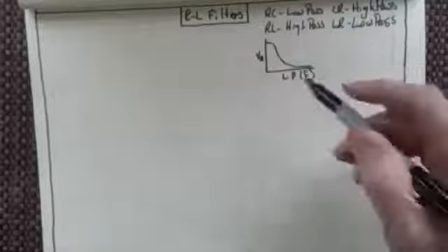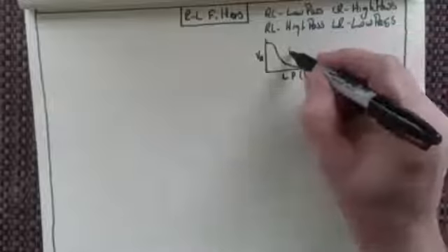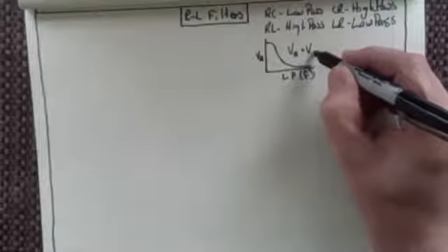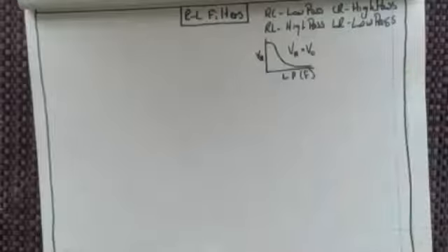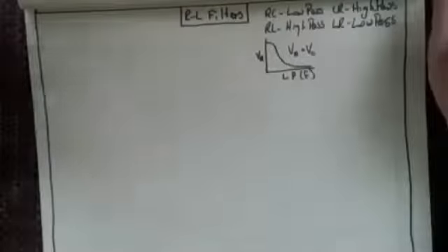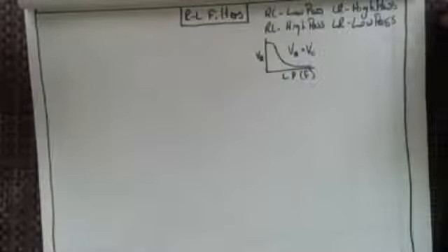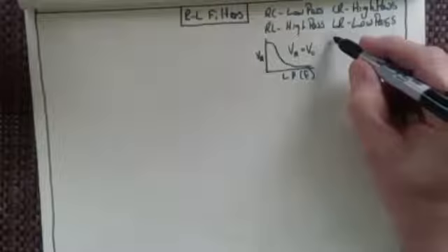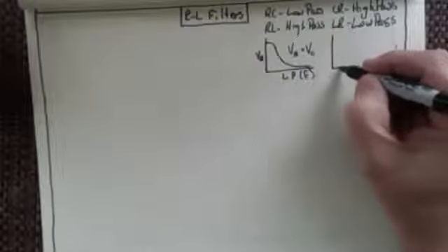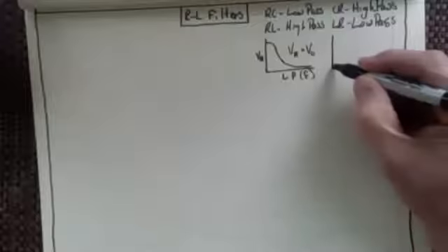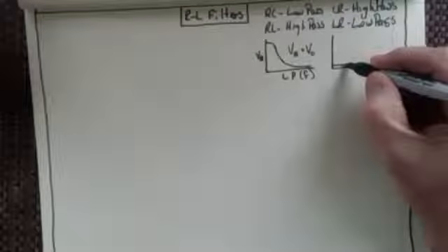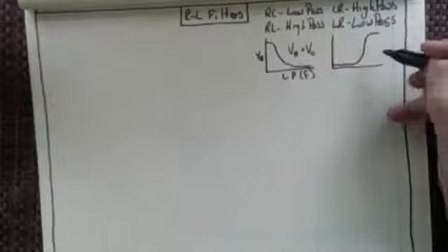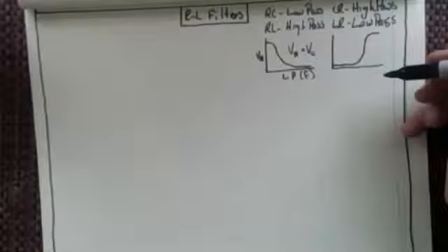So we'll say voltage at A. Of course, voltage at A in this is really the same as the voltage across the capacitor, isn't it? Since that capacitor, one end is hitched to ground and the other end is hitched to the point A, right? If we had the high pass filter, well, that's just the opposite. That means that it dampens out all the low frequency stuff and then allows the high frequency stuff to get through.